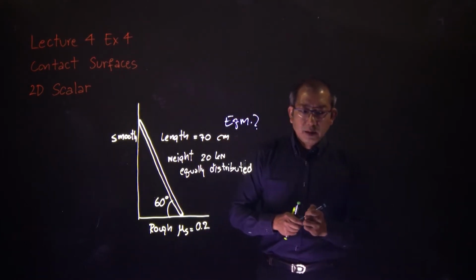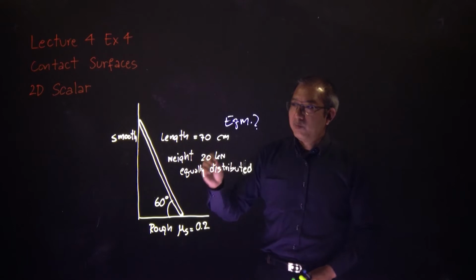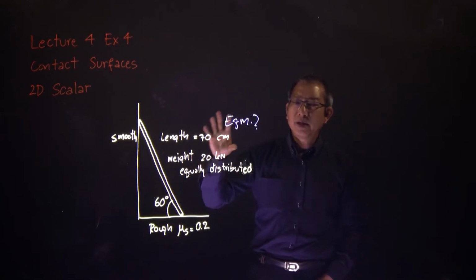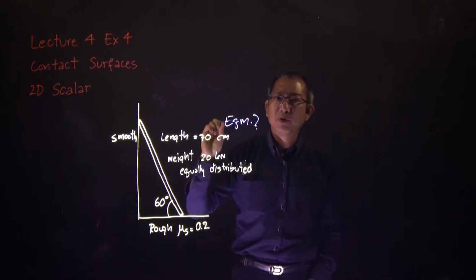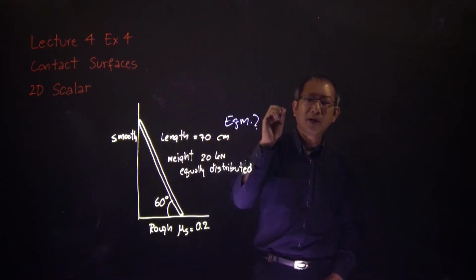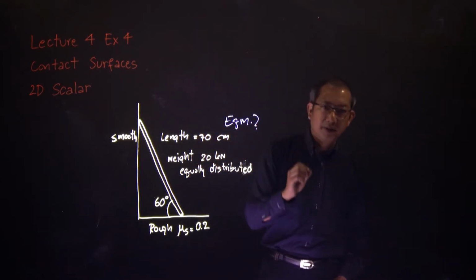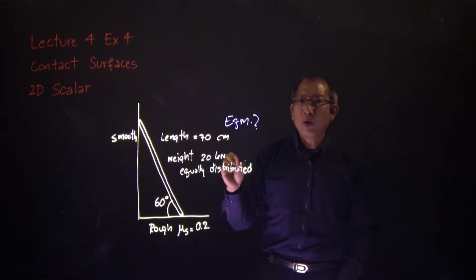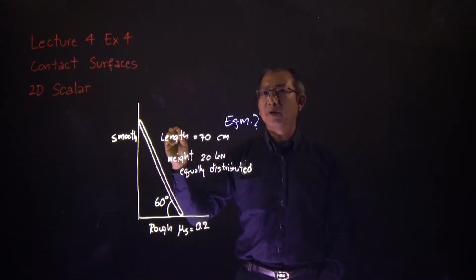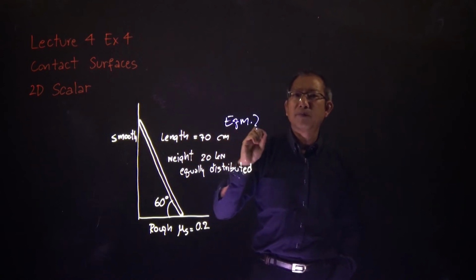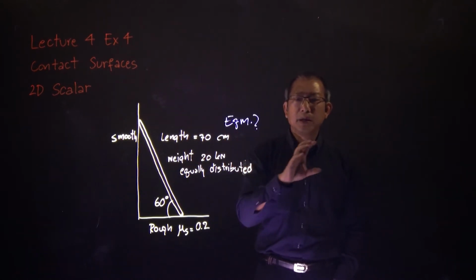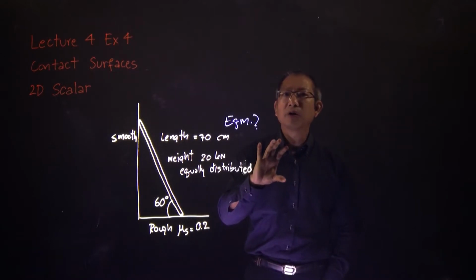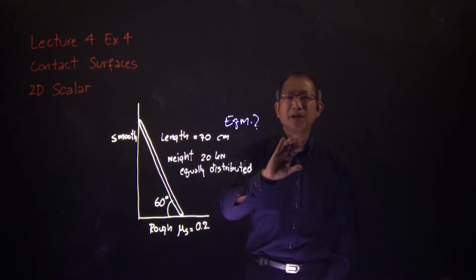Now this is the same thing. When we talk about equilibrium, this is the same thing as talking about resultant forces and resultant moment, with a different specific target though. This is not to calculate what is the summation of force and the summation of moment, because if it's in equilibrium, we already know the summation of force in any direction must be zero.